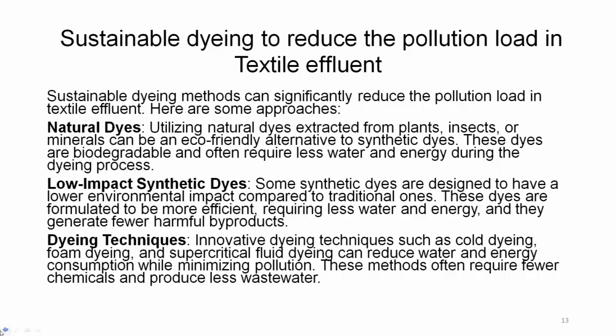If synthetic dyes have to be used, then those low environmental impact dyes should be used, so that they degrade easily. Techniques of dyeing that require less water should be adopted, like cold dyeing and foam dyeing. So, energy is saved in cold dyeing, foam dyeing requires very little water, and supercritical fluid dyeing does not use any water, but uses liquefied carbon dioxide as the solvent.